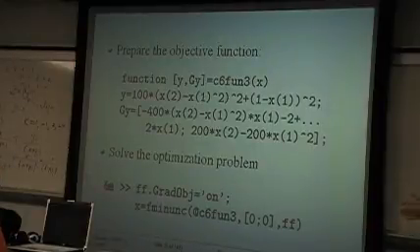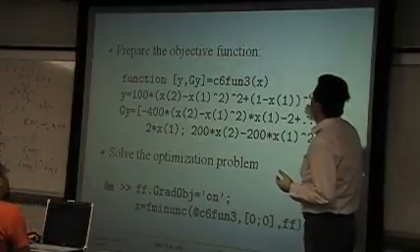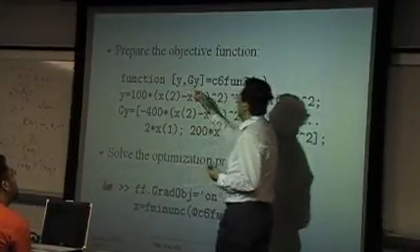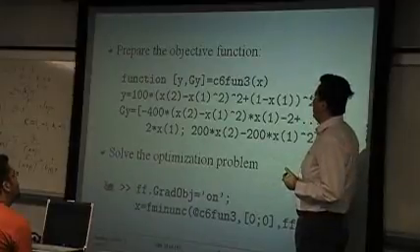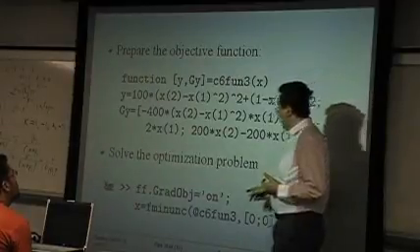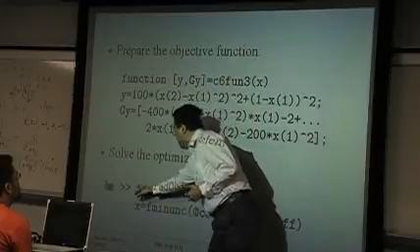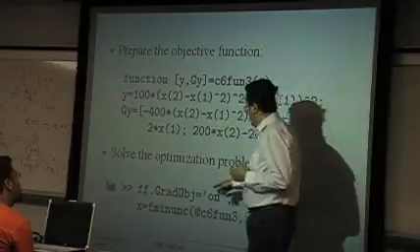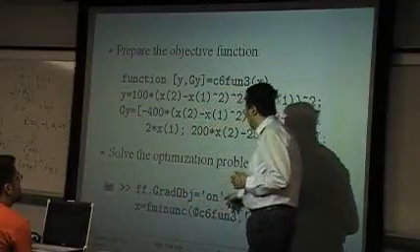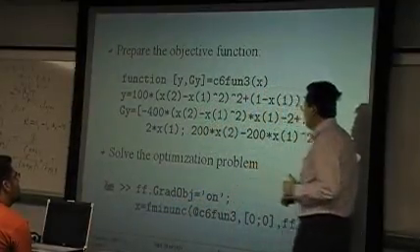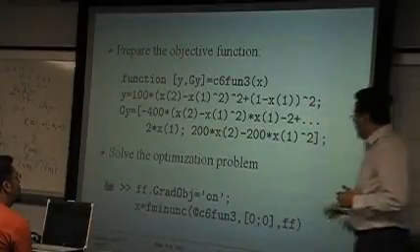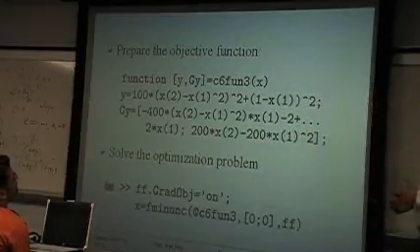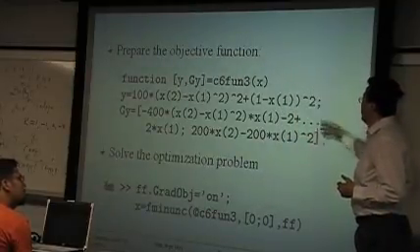And this is the one part we have to do to modify the objective function to return not only the objective function, but also the gradient of the objective function. Also, we need to set, there should be OPT. If I use my old code, there should be OPT. I should set the grad obj to on. The default one is off. If I set this one on, it means that we have the gradient information when described in this function.